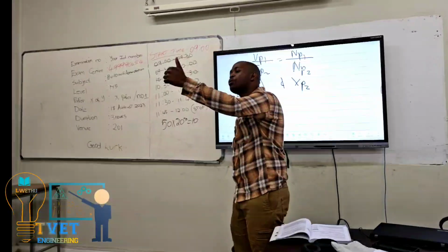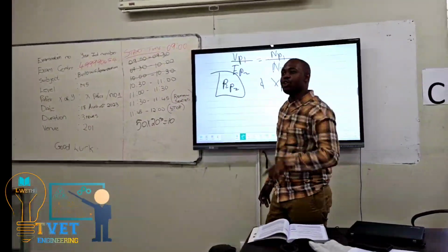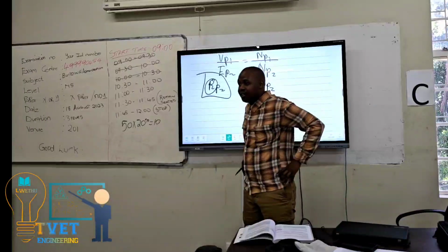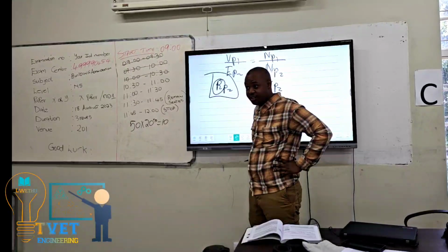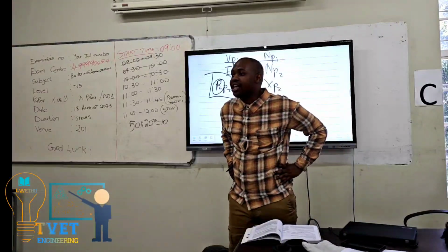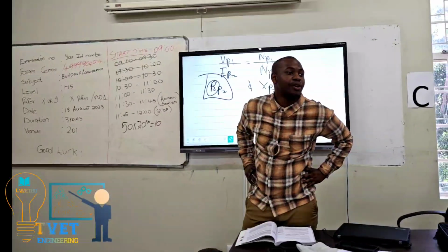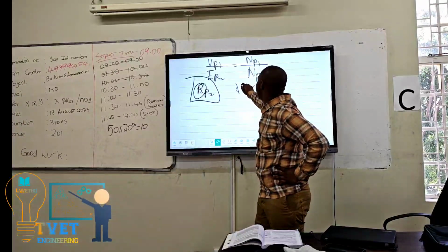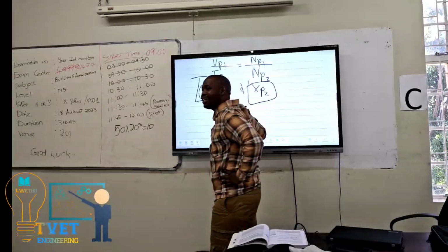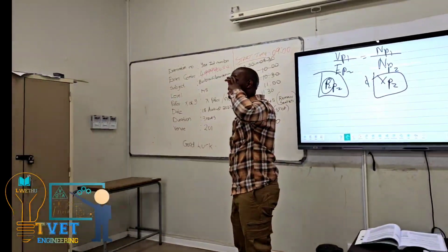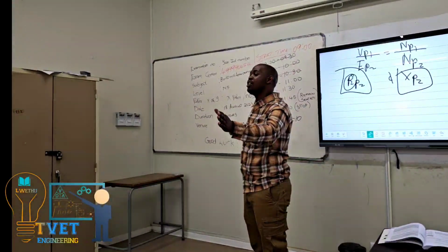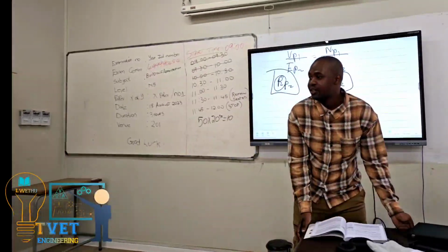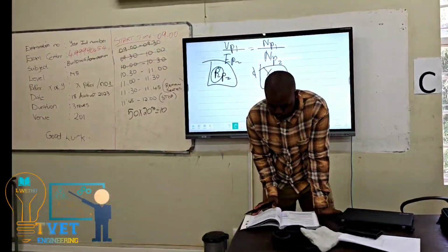The only value that is not frequency dependent is resistance. Resistance does not depend on frequency. The reactance, however, I must convert from a standstill value by multiplying by the slip.